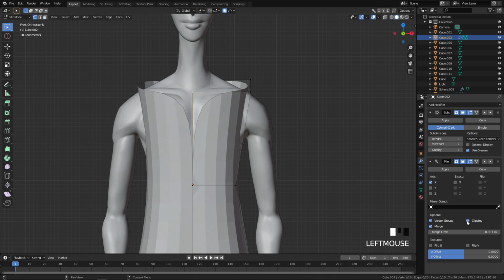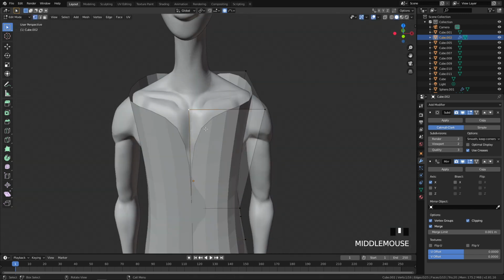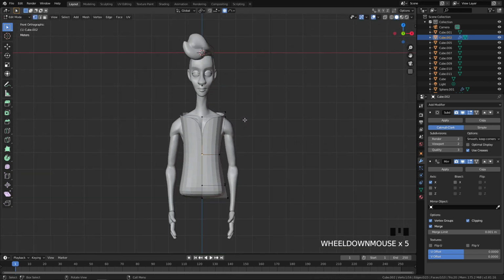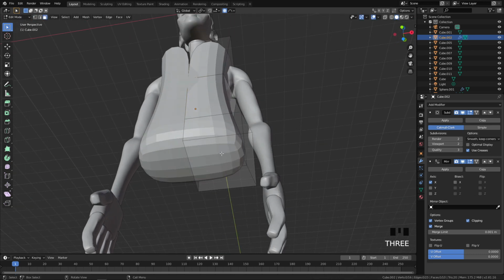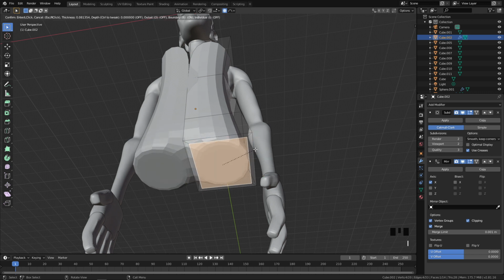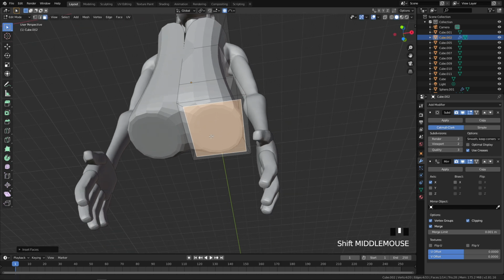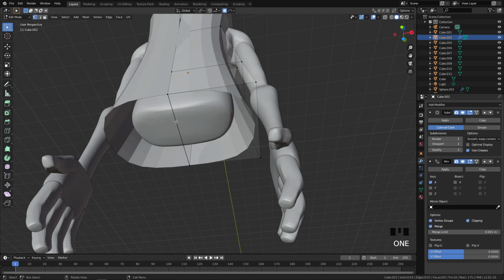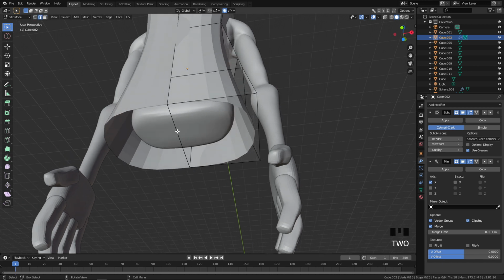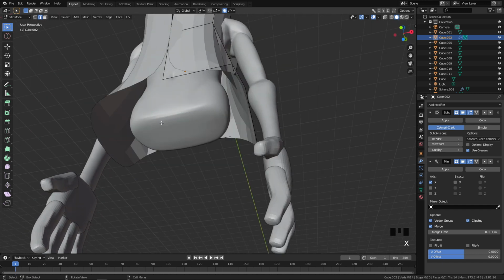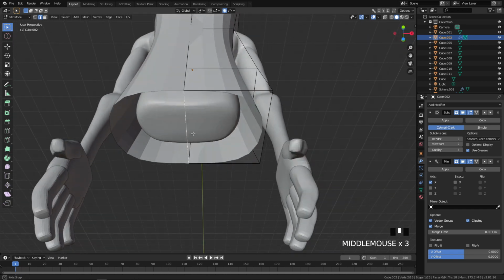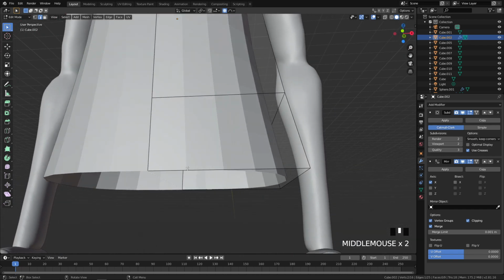And also we want to have clipping enabled, so we can't move these vertices to the other side. And yeah, it now looks weird, but we can also do the same with the bottom. So first, maybe we can inset it like this by holding I. And now we want to delete this face, and also this edge. So let's select it and delete it. Or wait. Okay, let's leave it for now, but later on we will delete it because we'll not need it.